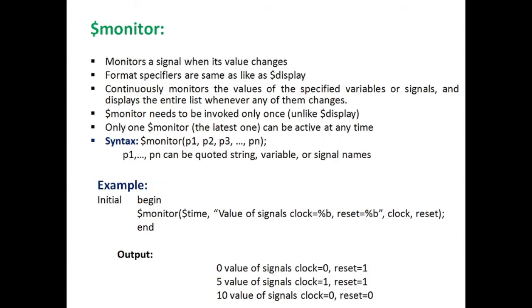Okay, then what is this $monitor? A speciality of $monitor is that it has a mechanism to monitor a signal whose variable value continuously keeps on changing. This facility is not provided in C language, it is only available in Verilog HDL.